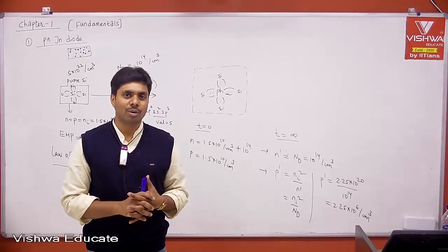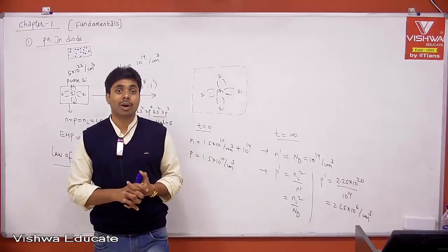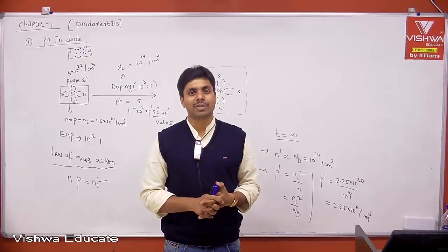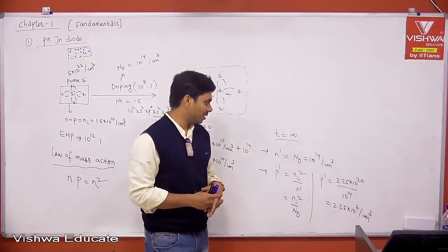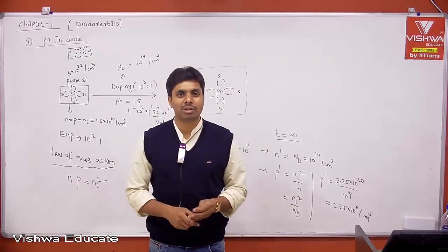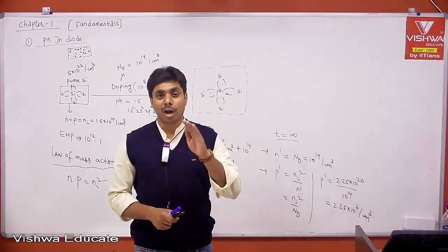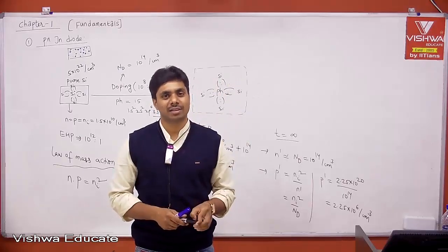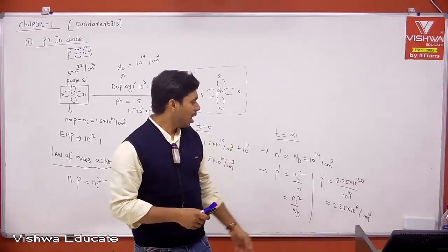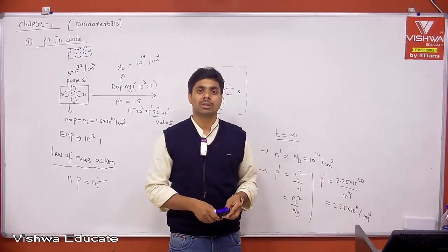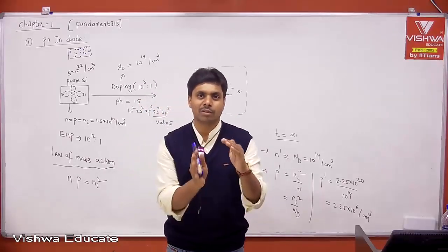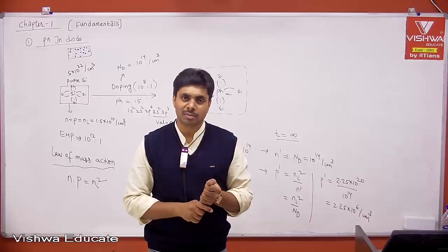Very high or very low? 22.5 lakhs per centimeter cube. Remember, we need to compare with respect to electrons. How many electrons are there? 10 to the power of 14 per centimeter cube means 10 to the power of 7 into 10 to the power of 7. What is that? 1 crore of electrons are there per centimeter cube. With respect to 1 crore, how many crores do you have? 0.2 crores. 1 crore versus 0.2. Unit is crores. Both of them have a common unit, which is nothing but crores per centimeter cube.